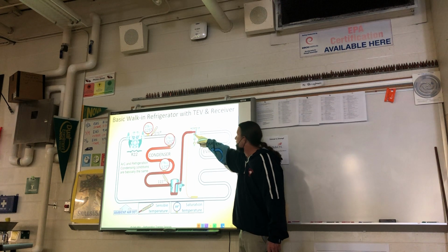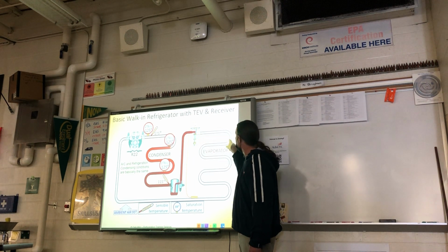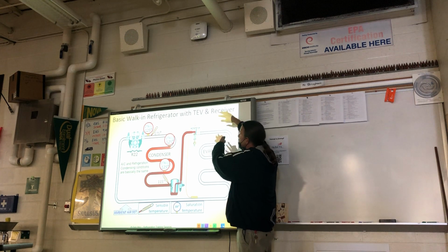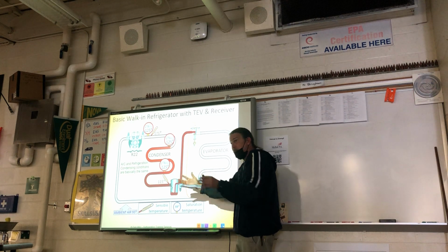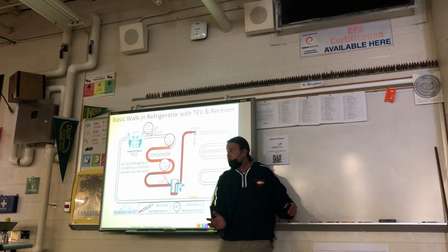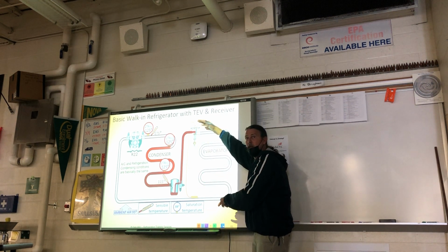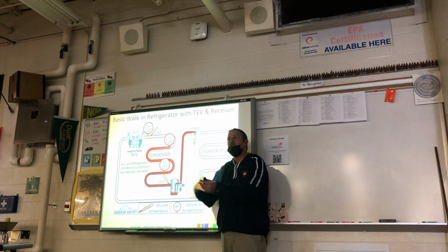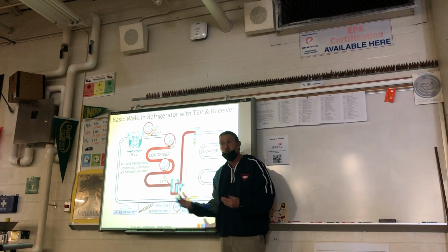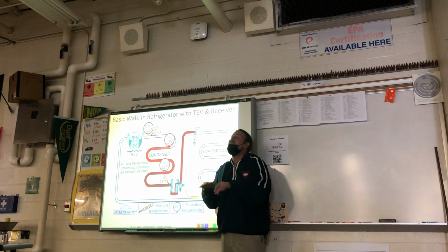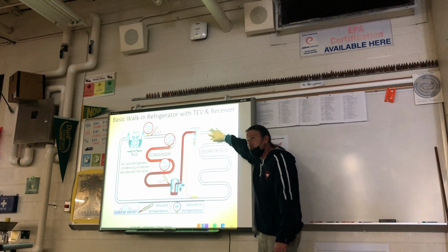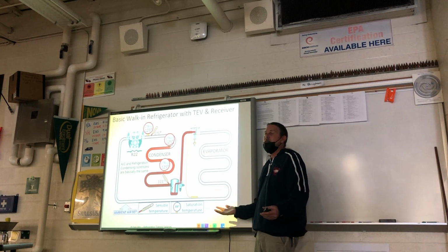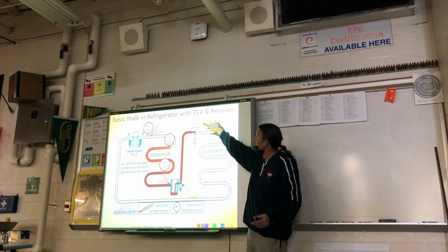Everything else is going to be the same, but now I have this that is able to control the amount of refrigerant, because now we're dealing with a walk-in refrigerator. When they have the food all loaded up right from the truck, and they've had the door open for an hour or two while they unload all the food, then they're going to need all the refrigerant in the system. But in the middle of the night when the restaurant closes down and the cooks aren't going in and out of the walk-in cooler anymore, they just need to maintain temperature, and they're not going to need all the refrigerant in the system to maintain temperature. So this is going to adjust depending on the load, because the load's going to adjust throughout the day, depending on how many people are walking in and out of that walk-in refrigerator.